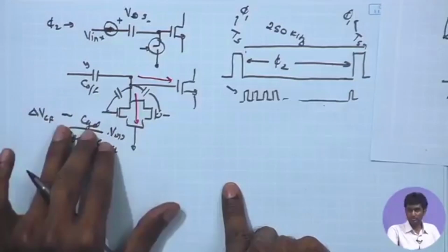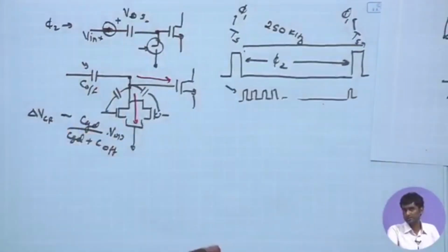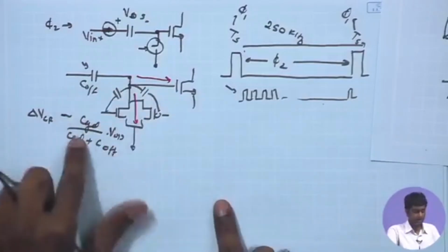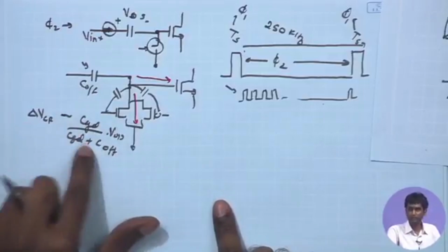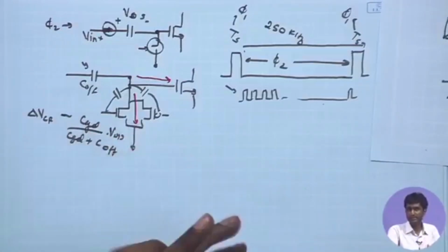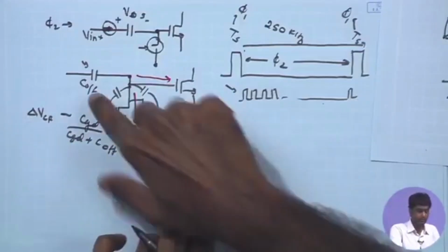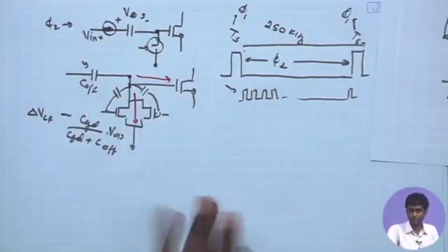Based on that we will again estimate that this C offset should be close to that sampling capacitor that we had, with a few picofarad. And if we add all other effects, the charge injection inaccuracy, the clock feed through inaccuracy, and add up these non-idealities, it may be at least around picofarad value required for the C offset, which is close to the sampling capacitor.